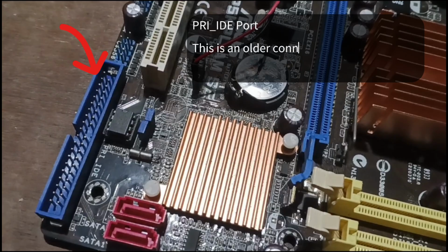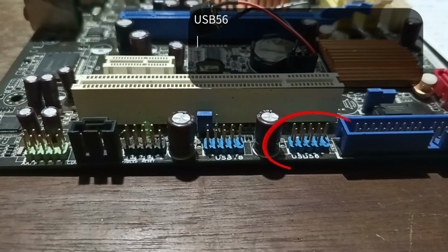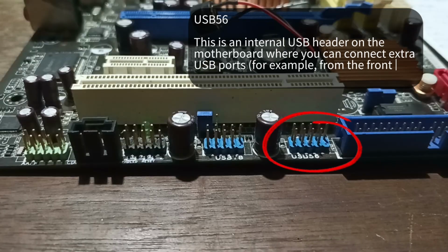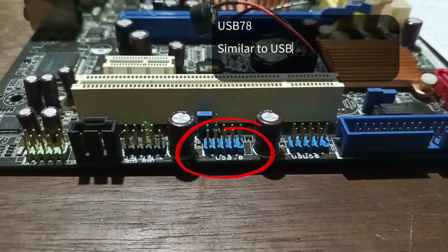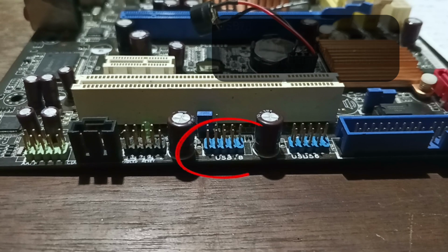This is an older connector used for old hard drives and CD/DVD drives. It has a wide ribbon cable, unlike SATA, which is smaller. This is an internal USB header on the motherboard where you can connect extra USB ports, for example, from the front panel of the case. Similar to the previous one, it's just another header for additional USB ports inside the case.